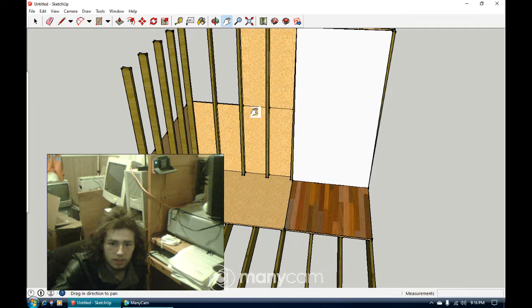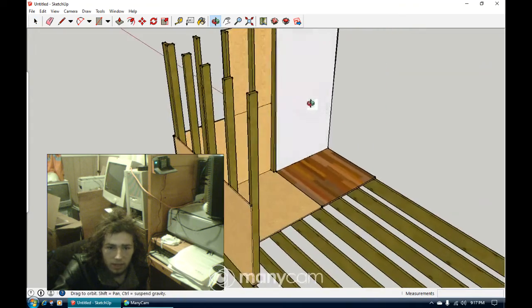Well, you can see this is traditional construction, with 2x10 joists, 2x4 walls, which is good to know because this could be 2x8s, this could be 2x6s, this could also be 2x6s. And then this could be, who knows, a 3/4 inch pine wood ply.